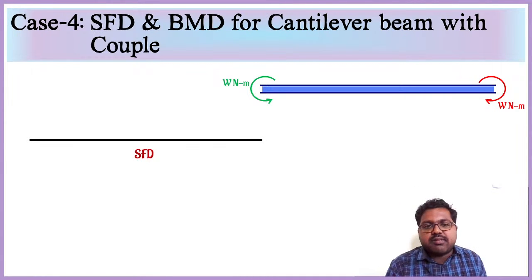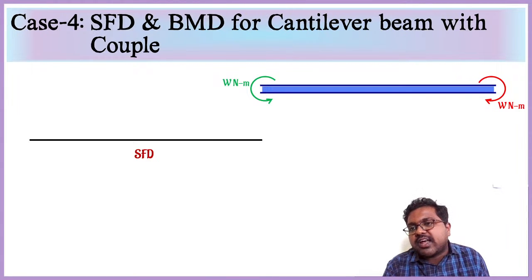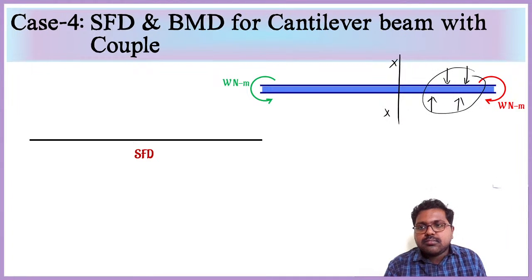When we are drawing the shear force diagram, nothing is there. If you want to draw a shear force diagram, if I consider a cross section XX here, on the right hand side or left hand side, we need to get some point loads or some reactions, then only the shear force will be developed.